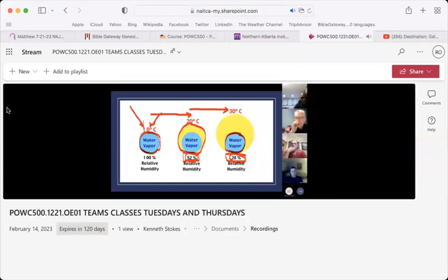When we bring outside air up from 10 or lower in Alberta, it's unlikely we're going to be as high as 100% relative humidity. We have very low moisture in the air normally. It's probably going to start at 28% relative humidity. So by the time we get into here, we're only going to be 14%. Comfort zone for humidity is recommended to be, and I'm just going to pick a random number, I sort of like 40. And I'll tell you why. There's some things in the book that are going to tell you.